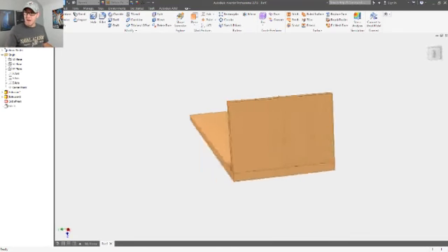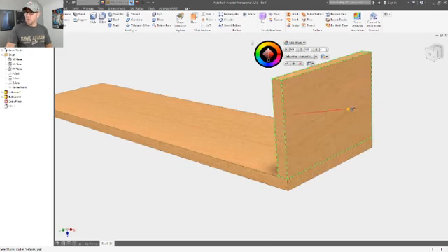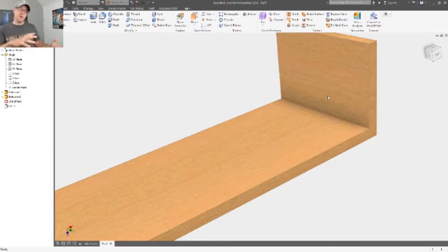And you may or may not get the orientation of that body, but because that body is a separate body now, whenever you do your body selection, you could actually come in here. So if I wanted this orientation to go opposite, I could pick that, go to my material adjust. I could have this one rotate to be 90 degrees. And now within one part, I have very easily adjusted the material orientation of different bodies. If this was one solid body, I would have to go through and do individual face selection of components.